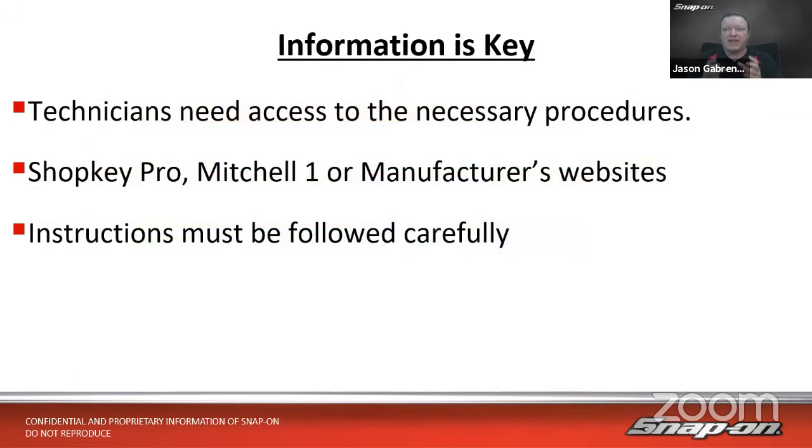So obviously we need access to these necessary procedures. Now I know Shopkey Pro and Mitchell have a wealth of that information in there. There's even a whole tab just for ADAS right from the main menu there, or manufacturers' websites. If you have a subscription to a manufacturer, that's not a bad way to go either, because that's straight from the horse's mouth, right?